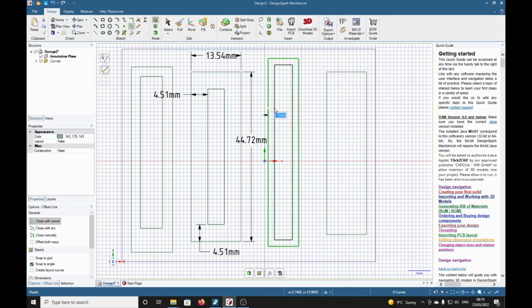So we can now type in a dimension for the shoulder distance. At the moment 2.17. Just type a 2 for a shoulder of 2 millimeters, and that's perfectly in the middle. Of course, knowing the width of the timber, we could calculate that so that the tenon or mortise comes out at the dimension we require.